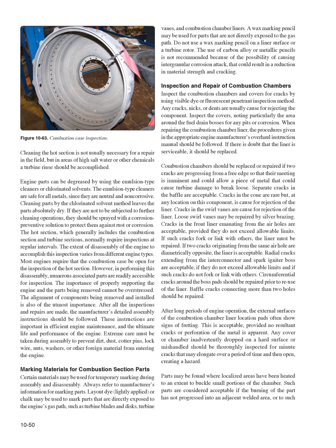After long periods of engine operation, the external surfaces of the combustion chamber liner location pads often show signs of fretting. This is acceptable, provided no resultant cracks or perforation of the metal is apparent. Any cover or chamber inadvertently dropped on a hard surface or mishandled should be thoroughly inspected for minute cracks that may elongate over a period of time and then open, creating a hazard.